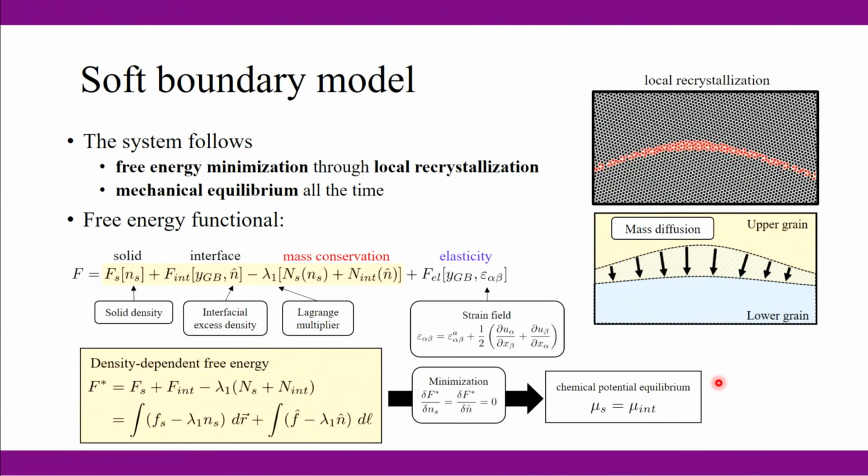Let me talk about the key ingredient we have in the kind of mean field theory, or theory for this solid-solid interface growth, all right? So, of course, the elasticity is important, so we will have a term that describes the elastic strain energy. So that's a very typical strain-stress product thing. And also, there's the interfacial energy, right? But the interfacial energy now is no longer just a certain number, and maybe you consider the surface energy anisotropy. You can also include it.